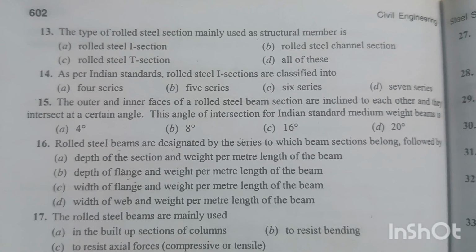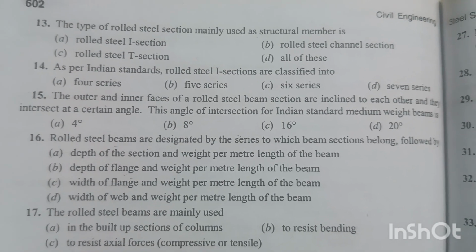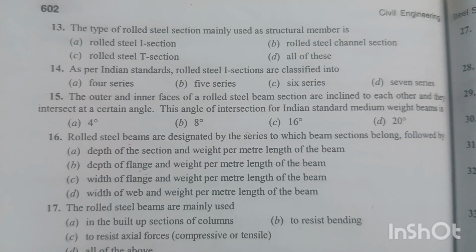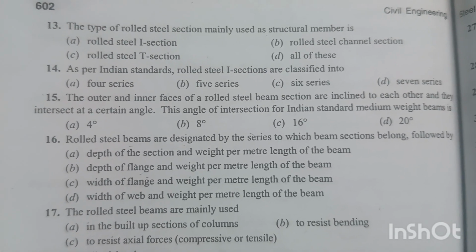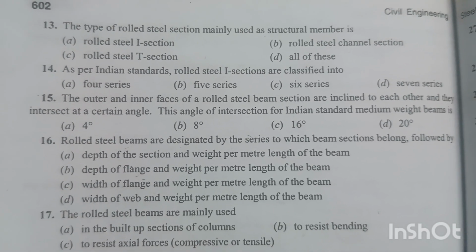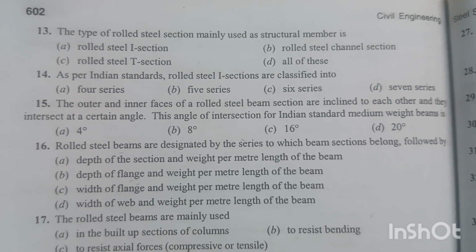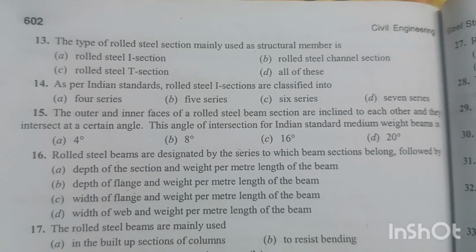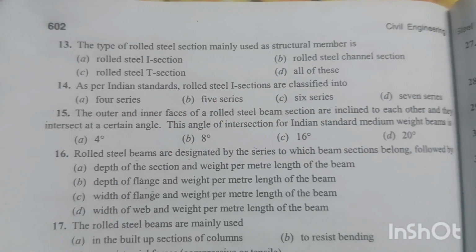Question number 15. The outer and inner faces of a rolled steel beam section are inclined to each other and they intersect at a certain angle. The angle of intersection for Indian Standard Medium Weight Beam is 8 degree. Option B is the right answer. Question number 16. Rolled steel beams are designated by the series to which beam sections belong, followed by depth of the section and weight per meter length of the beam. Option A is the right answer.